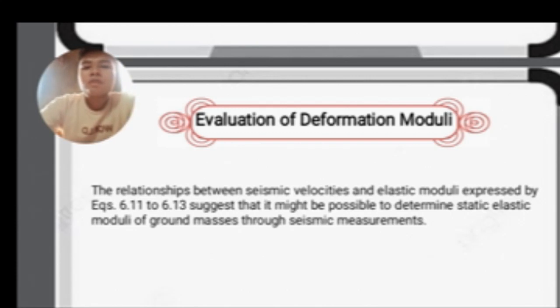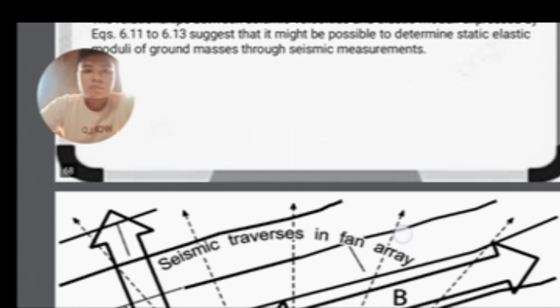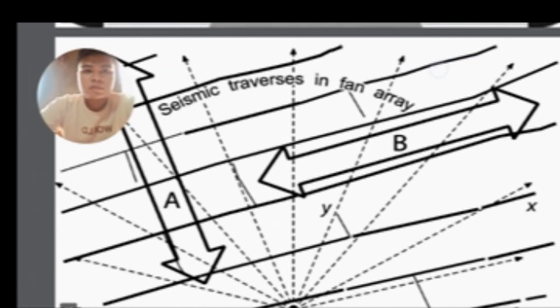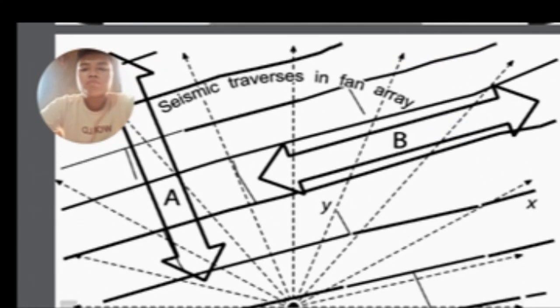However, there are many reasons why it is necessary to distinguish between statically and dynamically derived moduli. This illustration shows a plan of joint traces in a rock of homogeneous lithology. Joint X is persistent, frequent, and sometimes open, while joint Y is impersistent and frequent.